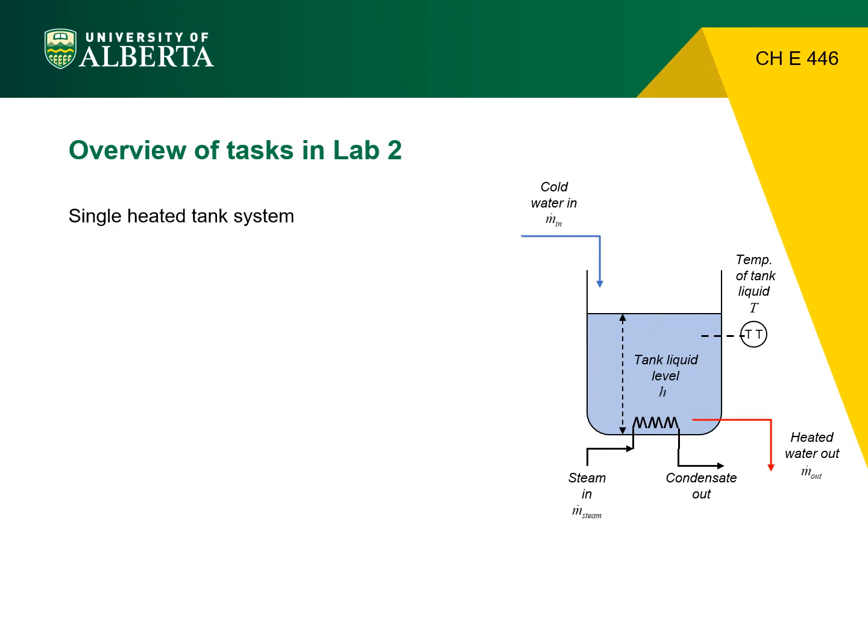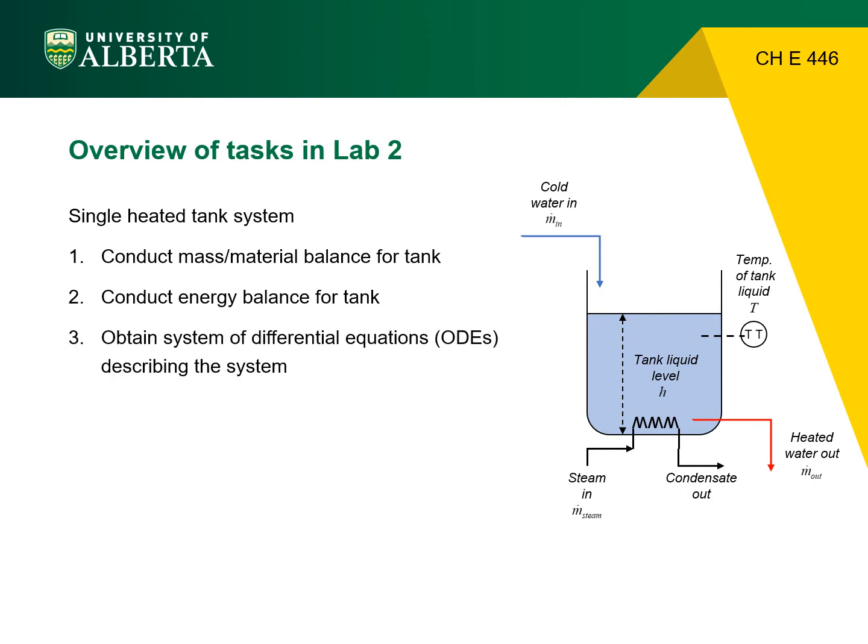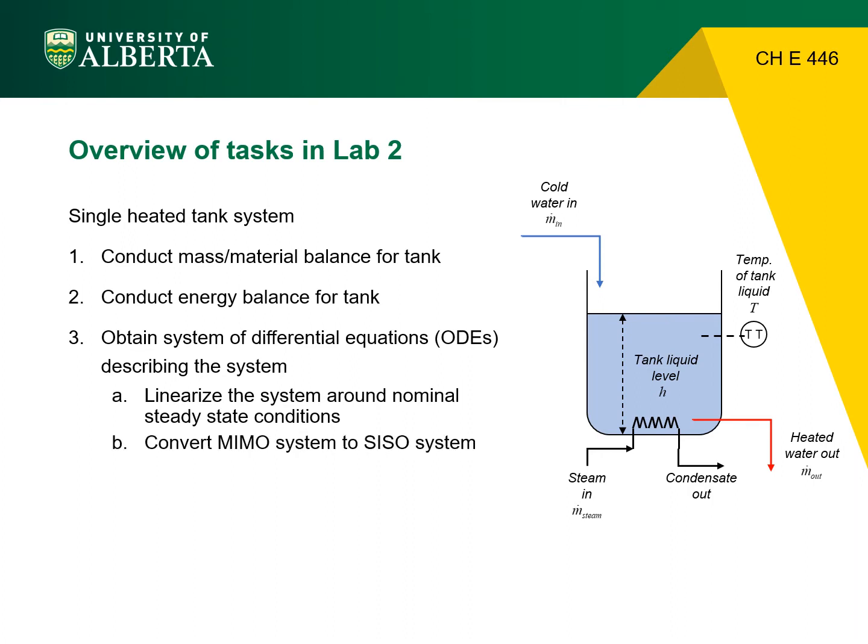For the single heated tank system, you are asked to conduct mass and energy balances for the tank. You are then asked to obtain a mathematical description of the tank system in the form of a system of differential equations. Then, you are asked to linearize the system around given steady-state conditions.